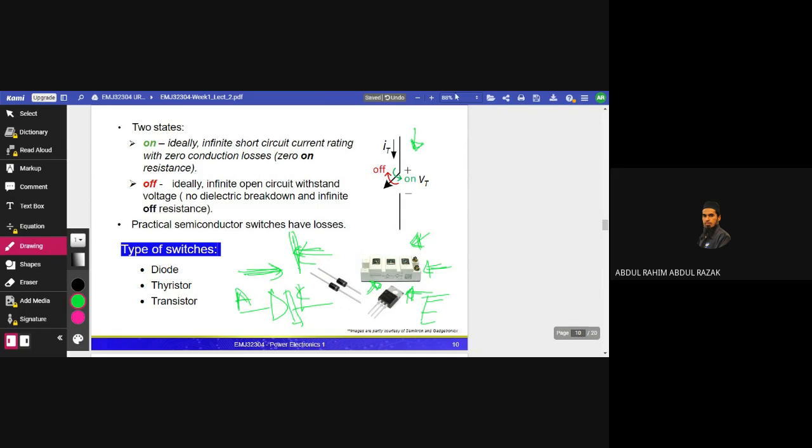One is the power that we deliver to the load. We have an AC source, we have a diode, we have a load. One is the power that is being used at the load. So the power delivered is equal to VI, or I square R. If we measure the load, we can measure the voltage drop across the load times the current that flows into the load.